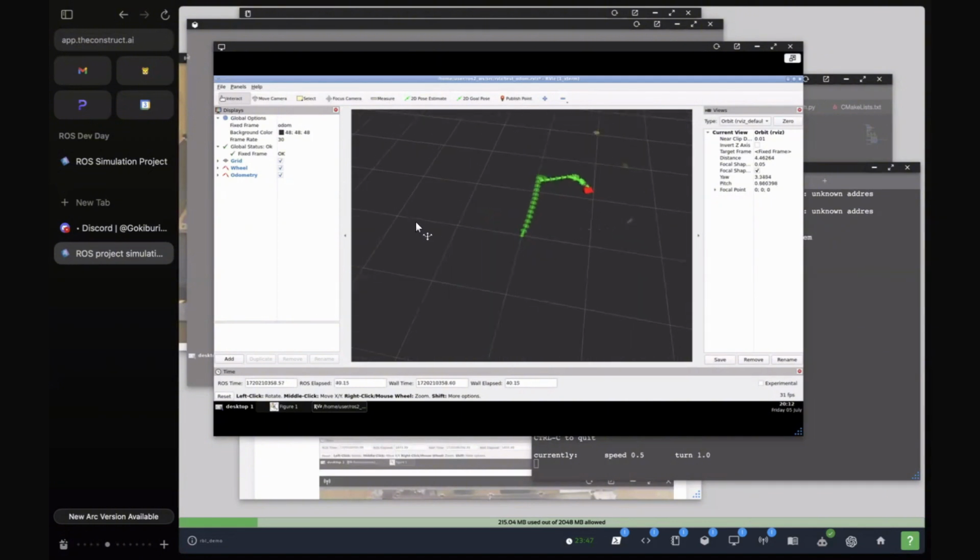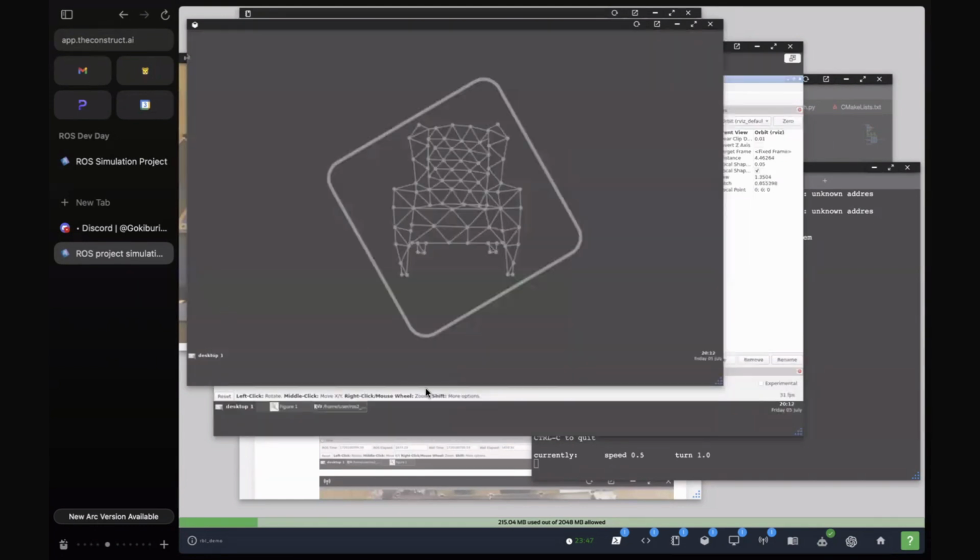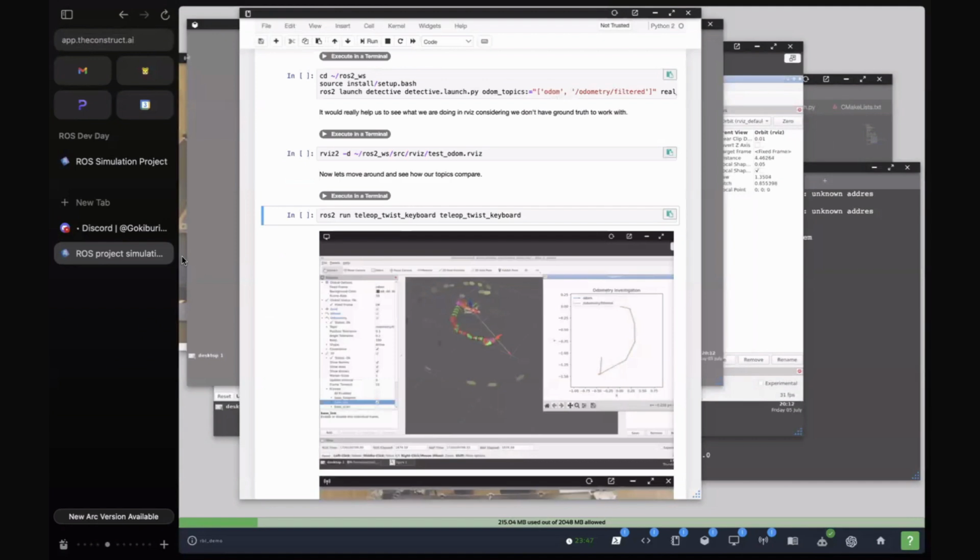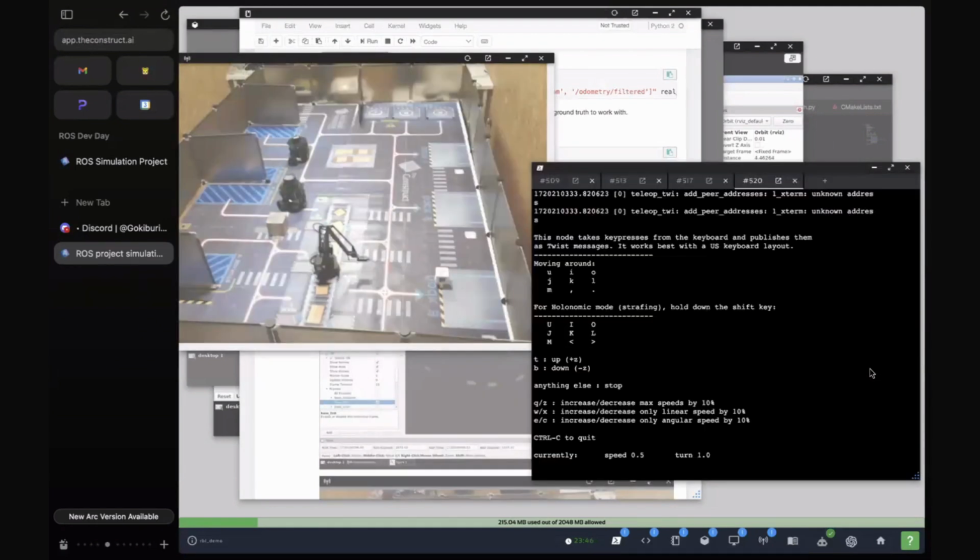And what you will see is right now it's almost exactly the same. So if I turn one off and turn another one on, it's in the same exact position. This is mostly because in real life, the odometry is actually not as bad as in the simulation, but we can still move around more and see more features that our filter gives us.